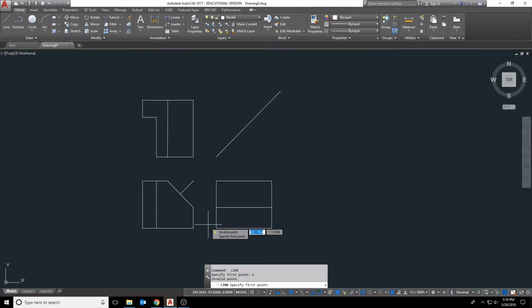So now if I offset that line 10 on each side, because it's a diameter of 20, that gives me the location for the extents of that hole. So if I draw this down at 45 degrees and I draw this down at 45 degrees, this is going to give me where it actually goes through this entire part.